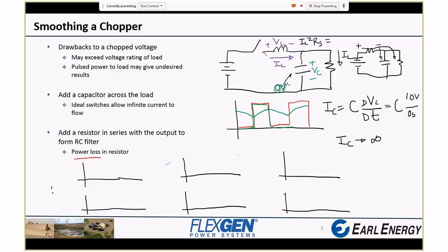All right, this is going to be battery voltage, current. We'll have the inductor, and we'll have the capacitor, which will also in some ways serve as the load. Maybe we'll add some axes over here for the load later. Okay, so what did we say for the battery? This is the switch voltage here. It's switching between 0 and the battery voltage. That's just what it's doing.